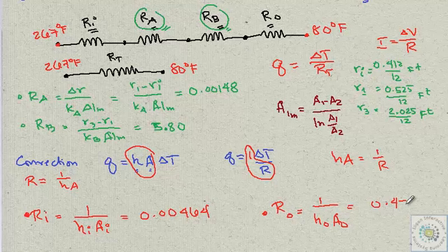As you can see, compared to the steam, the air offers a higher resistance because it doesn't offer good convective heat transfer, while the steam's resistance is small. Of course, if you want heat to flow, you want a small resistance, but if you don't want the heat to flow, you would like a higher resistance. So now I think we're ready.